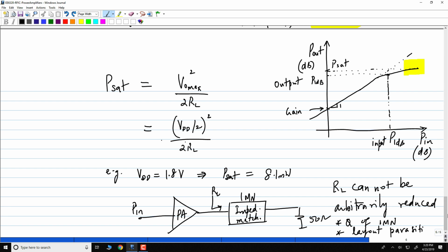You can use an infinite inductor. Just like an infinite capacitor is a voltage source, an infinite inductor is a current source. Okay, remember that. If I take an infinite inductor with a current I through it, this is identical to a current source with value I, because at any AC frequency the infinite inductor gives you an open circuit. The current cannot change through the inductor. Excellent.